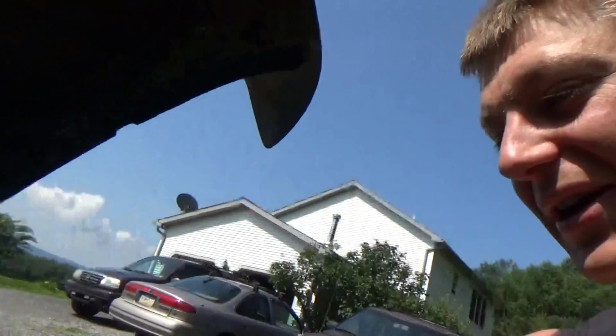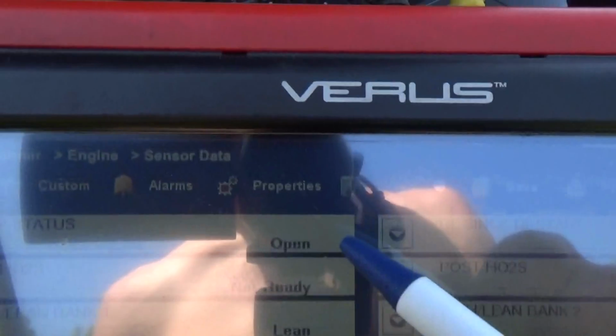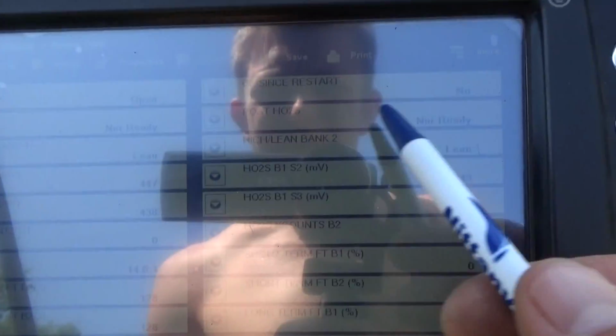It does start. So the long crank time, actually, if it doesn't have a cam sensor, it'll use just the crank to synchronize. That's why it's a long crank time. It all makes sense. But see, the oxygen sensors are staying at 450 millivolts. We're always in open loop. Obviously it's not using fuel trims. It's just running off of the MAP sensor and the crankshaft position sensor, because we're missing the MAF, we're missing the cam.